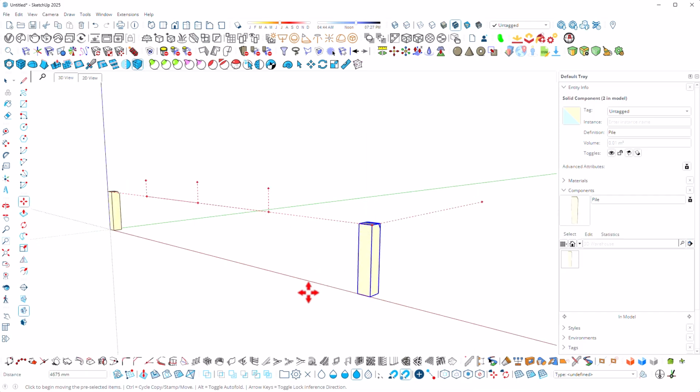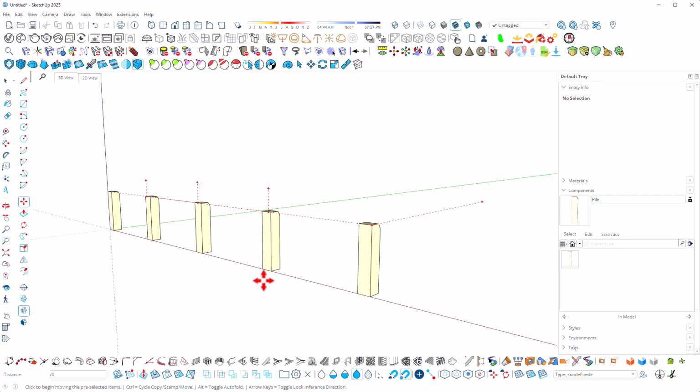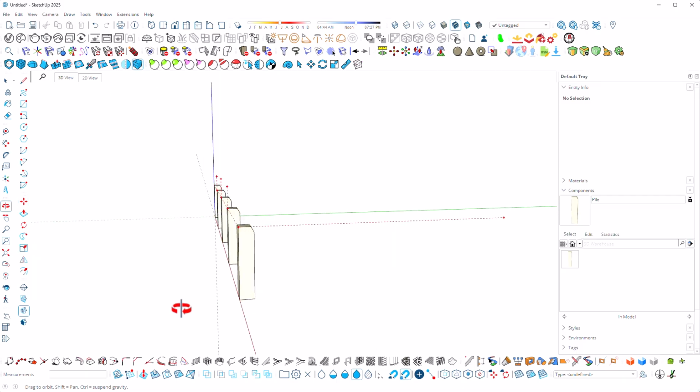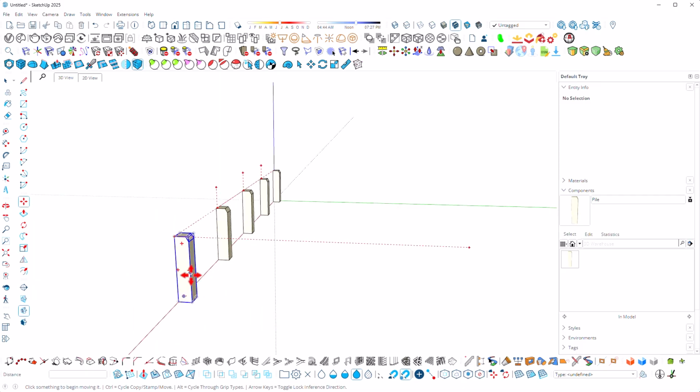Click to place it. Now, as you can see in this view, we've got 1, 2, 3, 4 divisions. So to lay piles there automatically, on your keypad, push divide or / 4, enter, and voila, you have your piles. Now we want these piles on the left to be transferred to the right, and then there will be 2 divisions, so we can divide 2 and automatically lay the piles in the center.